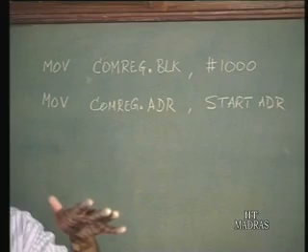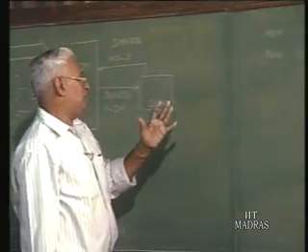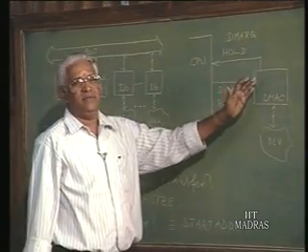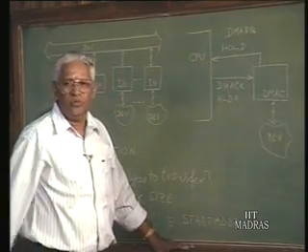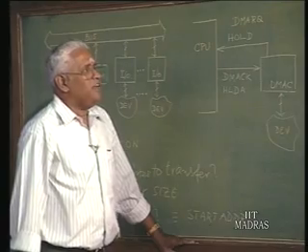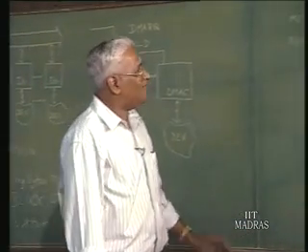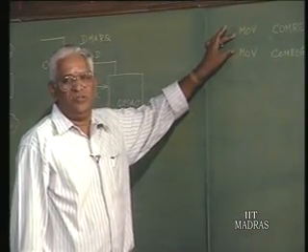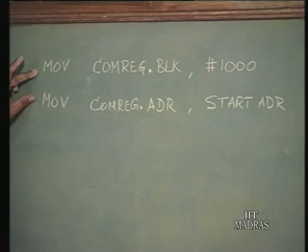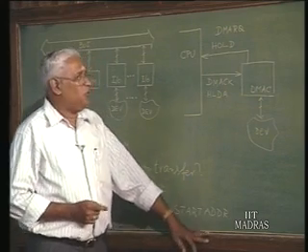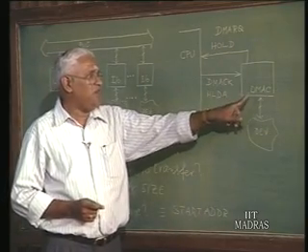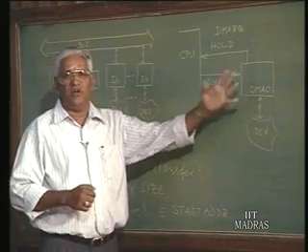When you write something into the command register, the CPU is issuing a command and defining certain parameters, what it should do, right. Fine. As far as the CPU is concerned, essentially these are the two instructions basically in preparing for DMA transfer, that is all, over, fine. Then the rest of it the DMA controller must do. So, in the case of the DMA, a study of the DMA controller is more important, what it does.